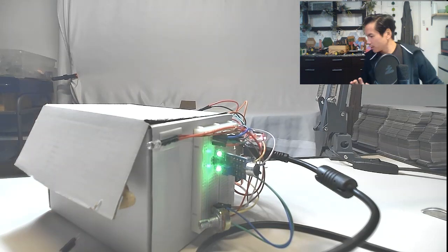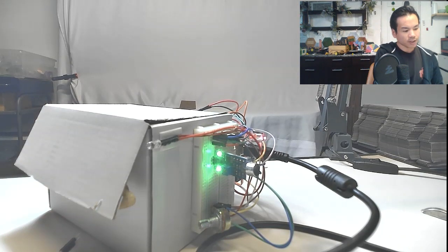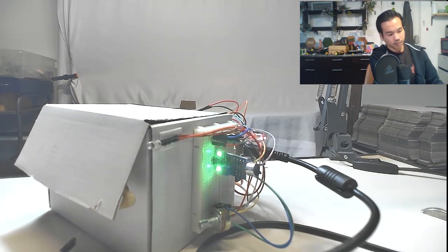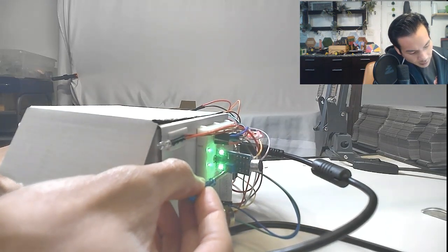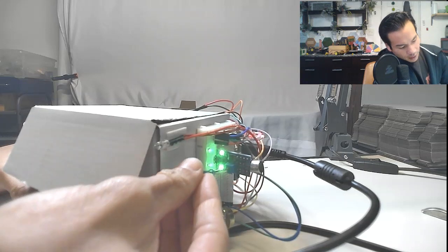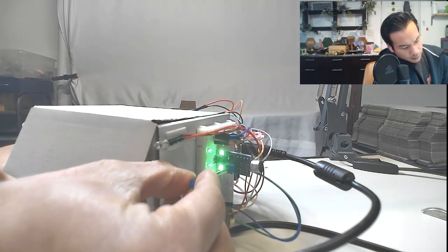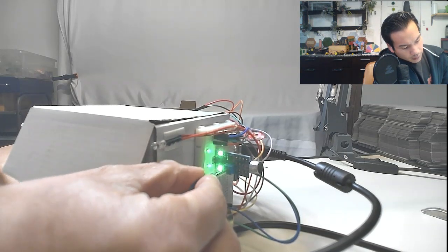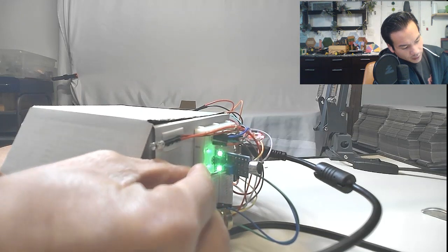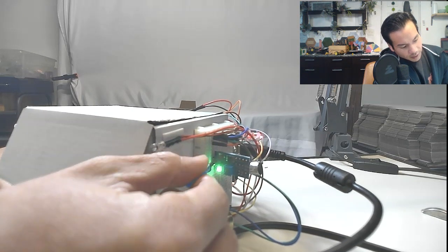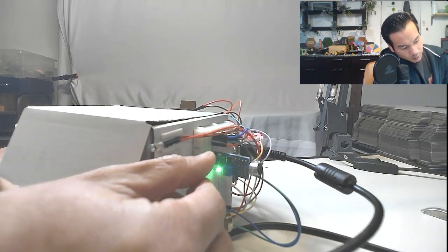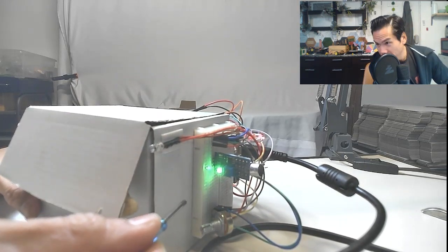So the first thing we're going to do now is we're going to get our screwdriver, right here, and let's put it into the little sensitivity adjustment dial, and let's rotate it. Which way here? I'm going to rotate it clockwise all the way till, and you'll see it, one of the lights here turns off, okay?